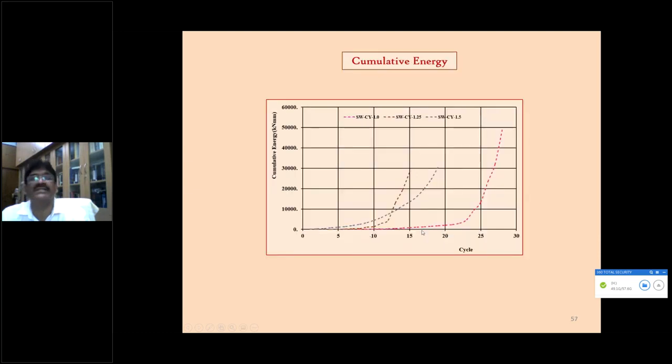The energy absorption in the walls: small size walls have more energy absorption capacity. As the volume of concrete in the shear walls increases under shear loading, energy absorption looks high in the case of smaller volume of concrete compared to the larger volume, due to something like Weibull's weakest link theory, or the probability of formation of voids in concrete.